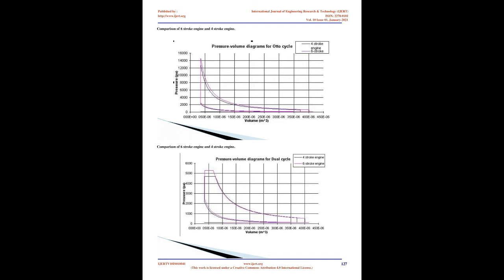At this stage the crankshaft completes 2 full cycles. In this stroke, less heat energy is expelled out when compared to the 4-stroke IC engine, as this heat has already been used to heat the air at high pressure in the air heating chamber. Fifth stroke, second power stroke: the heating chamber valve opens and the pure air, now at high pressure and high temperature, enters the cylinder as shown in the figure, which does work on the piston and hence it moves downwards, resulting in the second power stroke.